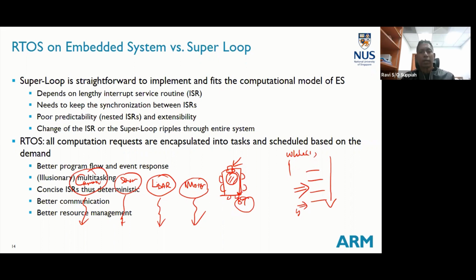Correct? And then what else must we think? We must now think, how will all these different modules or subsystems talk to each other? So there will be a lot of interaction. The LiDAR information must be sent back to some main routine that will decide what to do with the motors. And the sensor information will also need to be updated to decide whether to stop the motor or to move the motor. The camera data must be sent to the Bluetooth module to send over the network and so on. So I will then need to rethink how all these subsystems communicate.